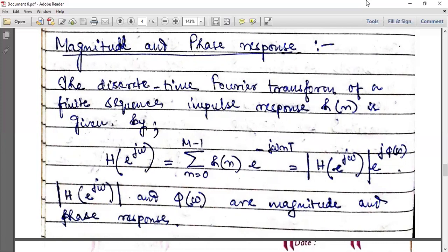And the third element that is required is very important. It is the delay element, which is needed to obtain the signals x of nT minus mT and y of nT minus kT, because x of nT minus mT is the past input at some instant, and y of nT minus kT is the past output at some instant.